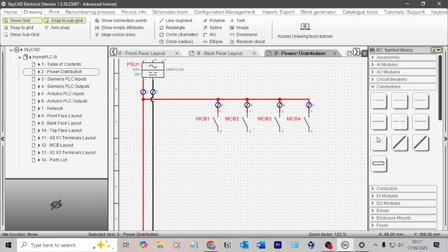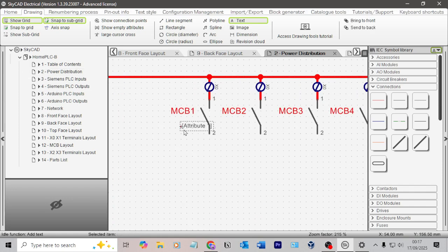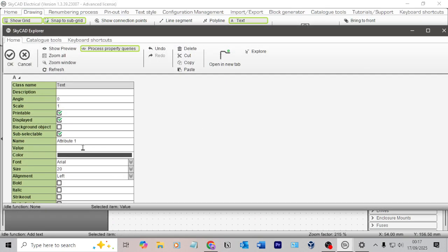So for now, let me just quickly stick some text here just so I don't have to keep running back and checking. So what is it? It's Siemens PLC there. What was the next one? Network switch. Why is that on a 2 amp breaker? That makes no sense. I mean, it doesn't even need to be on a breaker. Why would I ever want to turn off my switch?